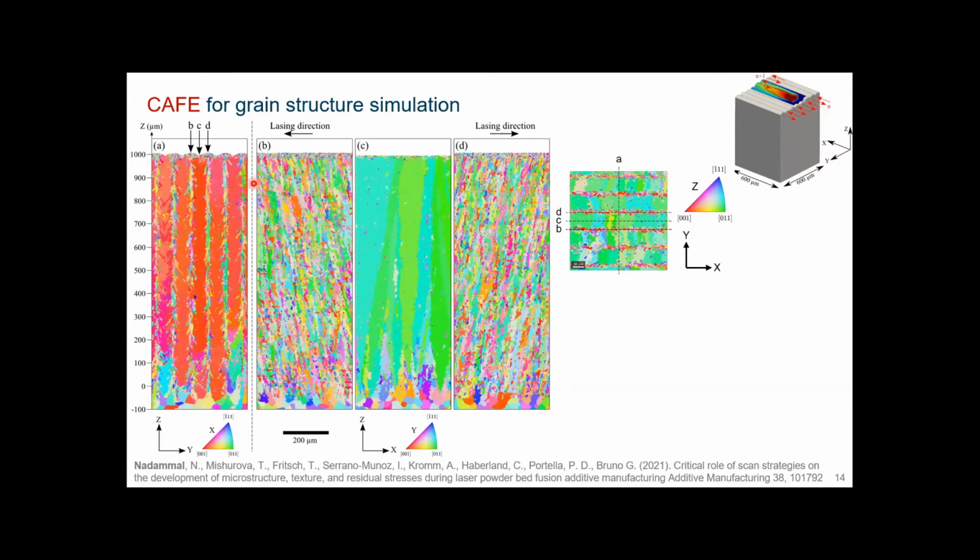And so you can now do cuts. You see here along this A plane, this is the left-hand side grain structure you have. It's all red, meaning that the grains have a very strong 1,0,0 texture. And this corresponds to the fact that the dendrites follow the path of the scan, basically, to make it simple.